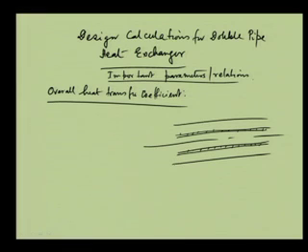So, what are the resistances that we know? There are 3 resistances that can exist. One is the film inside, then there is the resistance of the wall thickness, and another is the film outside the inner pipe. These are the 3 resistances to heat transfer from one fluid to the other fluid. In a double pipe heat exchanger, one fluid passes through the inner tube and another through the annulus, and in most situations it is a counter flow situation.